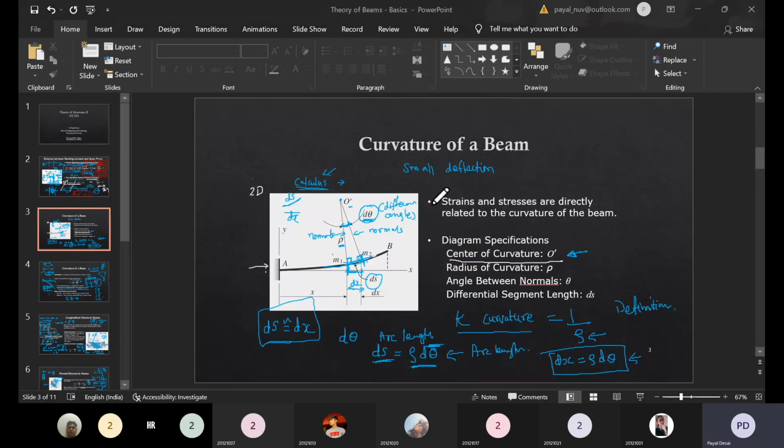Okay, now as I told you, I can also bring equation 3. If I substitute here, I can bring the fourth order differential equation in terms of loading. Okay, so let us write dv by dx. So in place of v we will write this equation. So substituting equation 3 into 4.